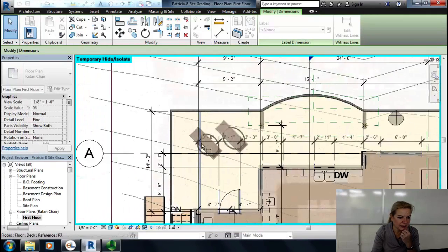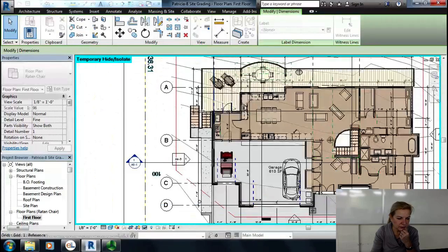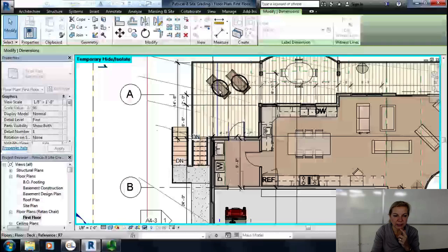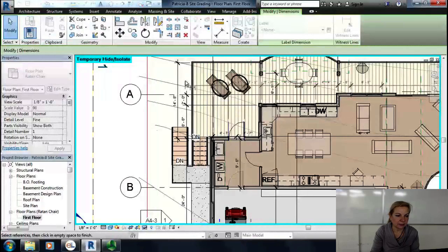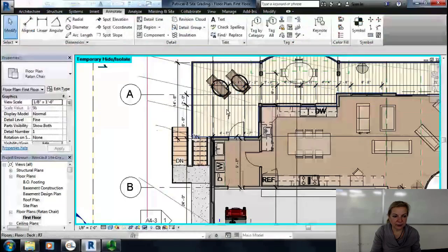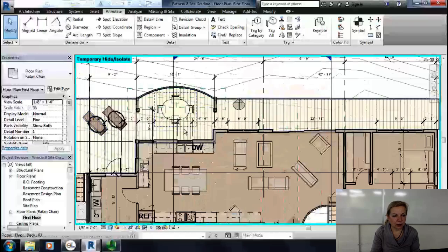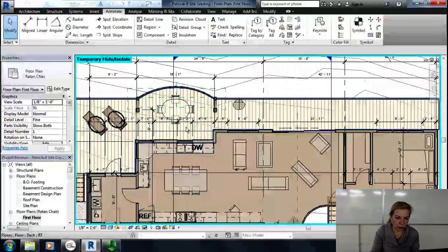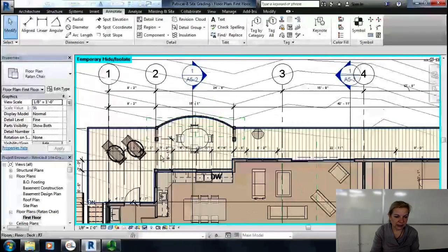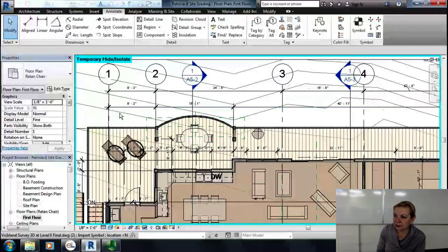And then if there is nothing else, double check that you've covered all the corners. And remember, no enter, no escape, click on the empty space. And now I have dimensions that are a continuous string. They cover all openings from jog to opening, wall to the end of jog. That's my first string. My second string is the actual jogs in the walls, because you have to think about different contractors that have to have that information, right? So it's all really common sense.